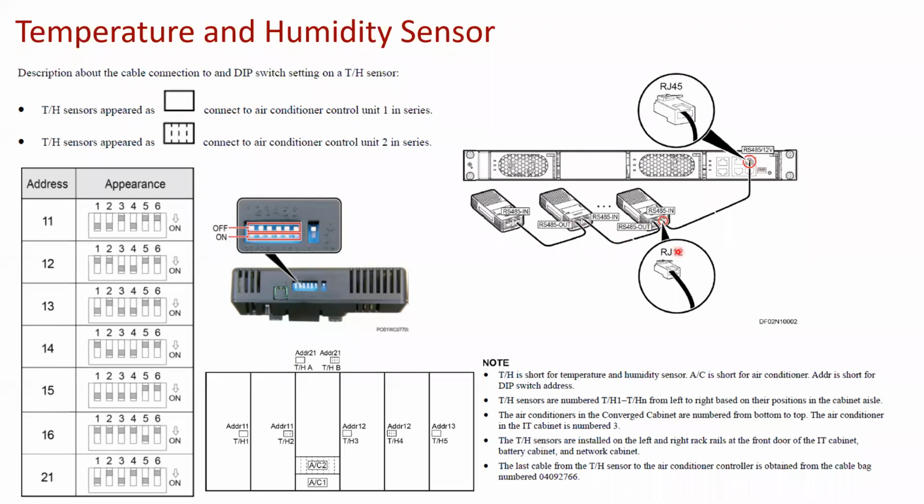For the ECC connection point of view, it is already controlled as RJ45, and for device to device it is RJ11. So it is easy to understand which cable needs to be placed where, and easy to operate. So you can see here the two sensors, one is a line sensor, one is a blank sensor. We can have the two paths and two loops, and the DIP switch and toggle switch can be set accordingly as per our design. You can see in this entire arrangement, two sensors are outside the data center, to manage the environment of the whole data center room.